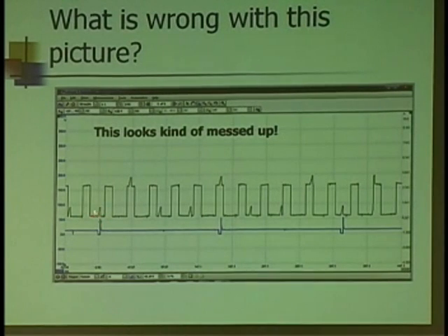If you look closely, this is actually the injector current pattern, that little somewhat of a triangle. And it's there, the same amplitude and shape, but it's riding on top of something else. So when this device, whatever that may be, is turned on, and the injector is turned on at the same time, I'm reading total current flow through that fuse.